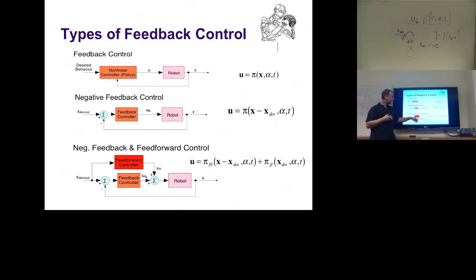The feedback controller is the error correcting controller. Remember, the feed-forward controller has no feedback. Here, the signal is directly coming from the desired state, going up here to the feed-forward controller, and then to the robot. It does not get feedback from the environment. So in this way, the feed-forward can only give you the right amount of pushing forward. The feedback controller does the error correction, which is really important. Without error correction, you cannot be stable. Without someone telling you how much you're off from your target, you will not find home at some point. So if you close your eyes, you will just deviate more and more, and instead of going to downtown, you will end up at the coast.